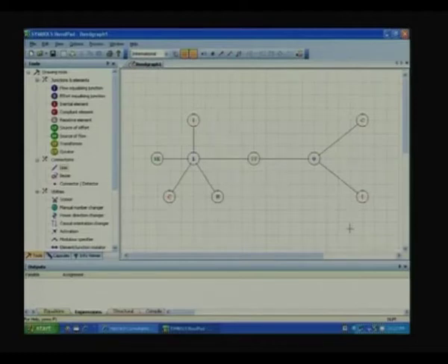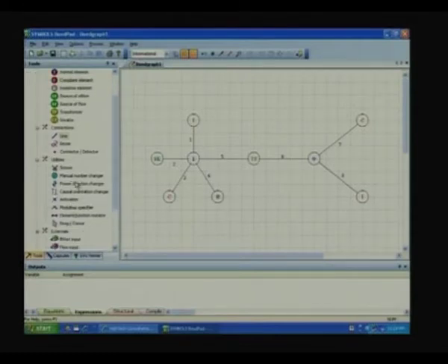Okay. So, the basic bonds are drawn up. Now, what we normally do on the paper is to put the numbers, right. Now, this numbering can be automatically done. So, at the top you will find an icon for numbers, right. The moment you click it, all the numbers are given arbitrarily, and you can change any of these numbers, for which there are icons like this. If you press this, it will allow you to change the numbers.